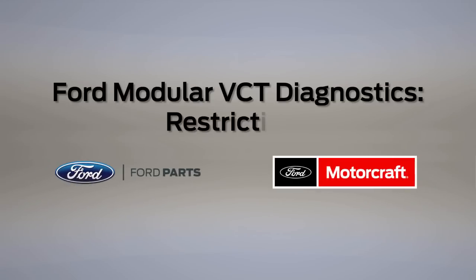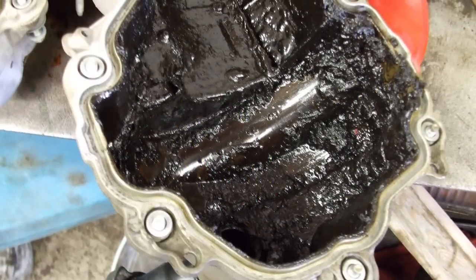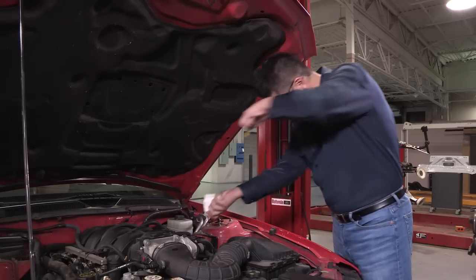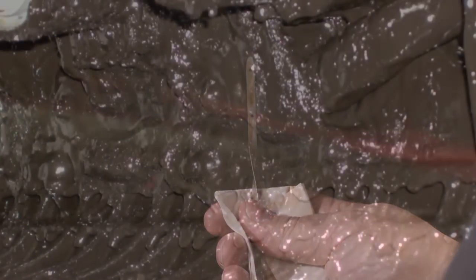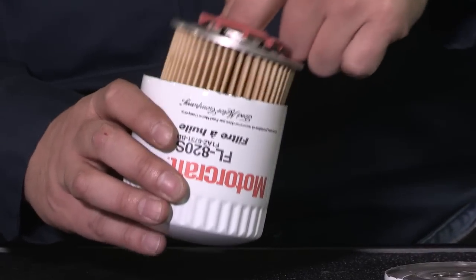When checking a modular 3-valve engine for a restriction in the lubrication system, first do an inspection for sludge. You may have already inspected for a general lack of maintenance, but also verify that no sludge exists in the engine. Sludge can lead to repeat repairs. The first place to look for clues is inside the oil filter.